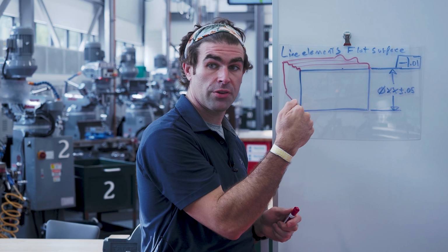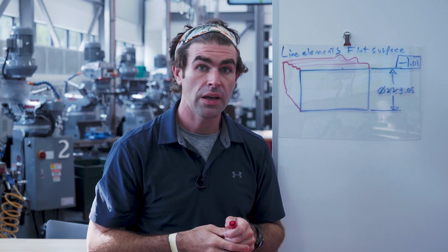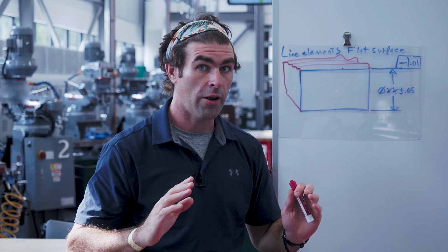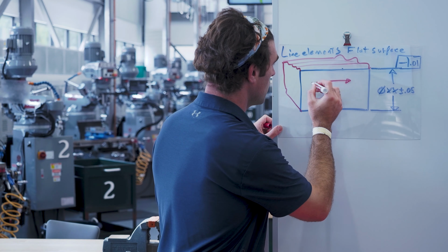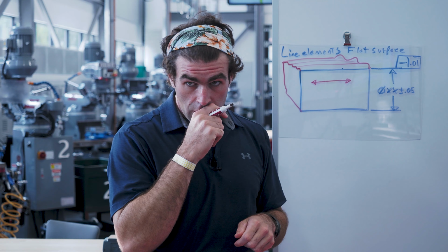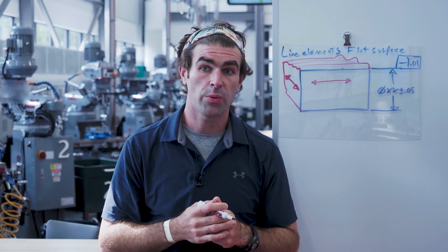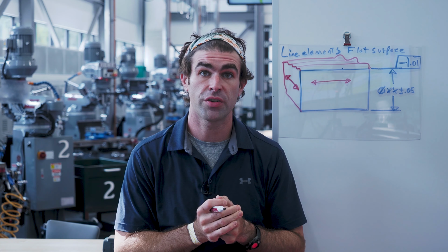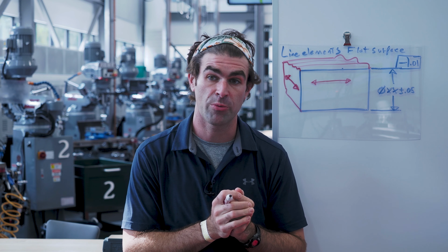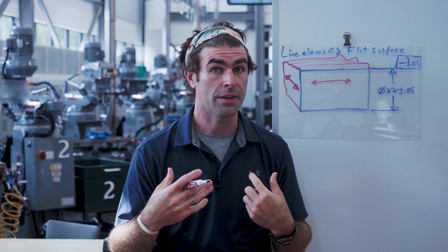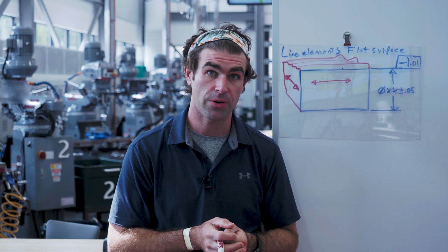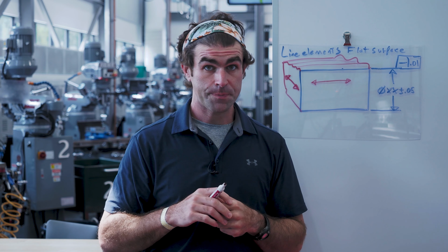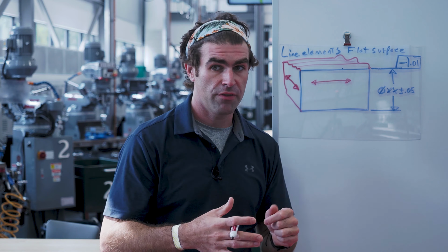And the other direction, so going toward the paper, or in this case, the whiteboard, there's no requirement for that 10 thou. It only applies in one direction, so this way. The other way, we still have that 100 thou of total tolerance. There's no requirement for it to be straight. So you can end up with parts that look like a corrugated roof, which is what I tried to capture right here.